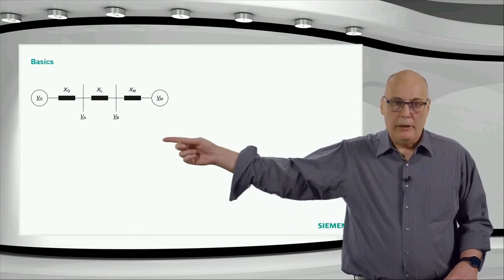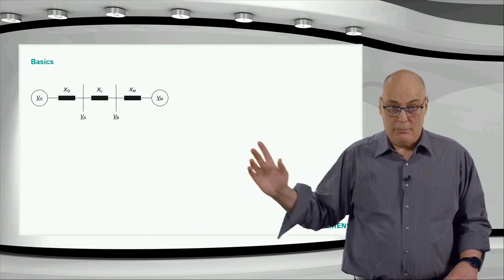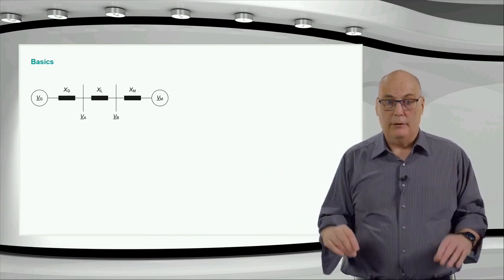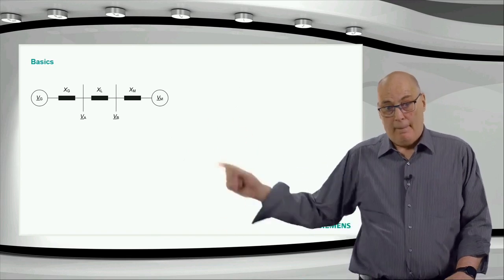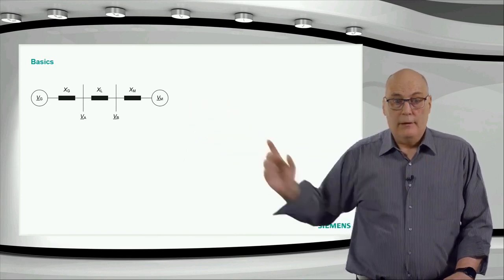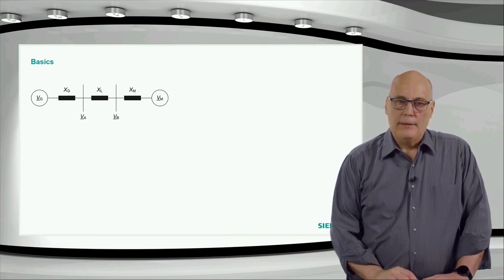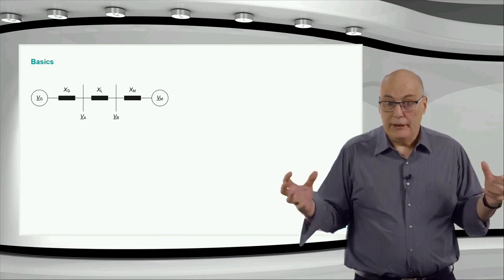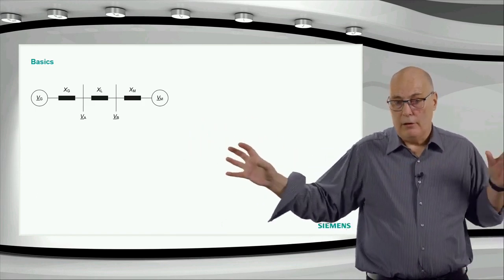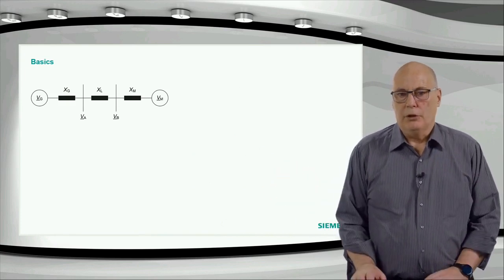So our relay would typically be at the VA, that would be the one bus bar on the left. VB is a bus bar on the right, not the A phase, B phase, sorry. So left-hand bus, right-hand bus, VA, VB. And then the load side impedance, the load impedance on that side. One can typically also consider this to be two sections of a transmission network, the generation side close to the generation and the VM close to the load side of a transmission network.